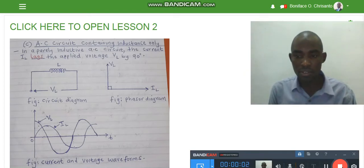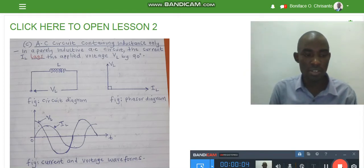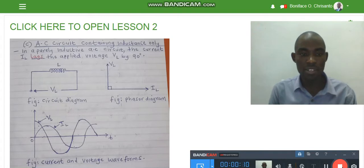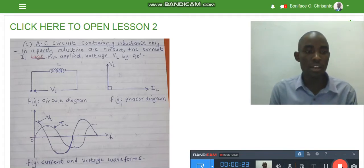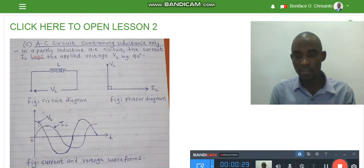Hello everyone, today we're going to discuss AC circuit containing inductance only. Sometimes this topic is referred to as a purely inductive circuit. It's a circuit which has got only an inductance in that particular circuit. So in a purely inductive AC circuit, the current lags the applied voltage by 90 degrees.